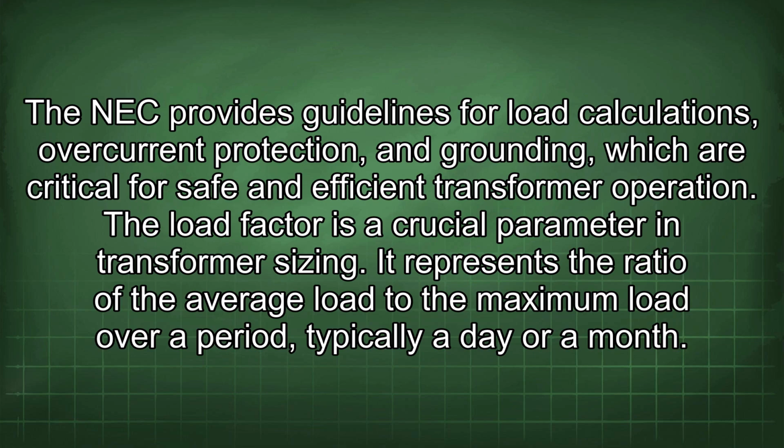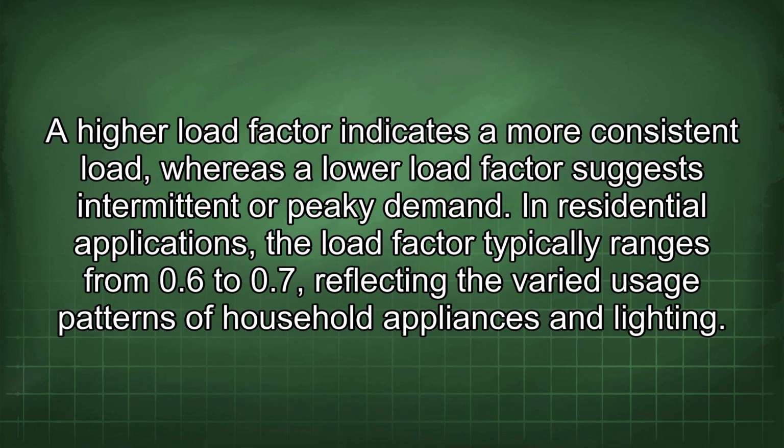The load factor is a crucial parameter in transformer sizing. It represents the ratio of the average load to the maximum load over a period, typically a day or a month. A higher load factor indicates a more consistent load, whereas a lower load factor suggests intermittent or peaky demand.